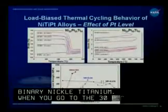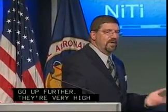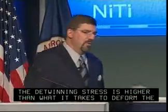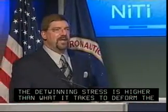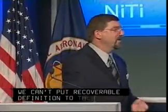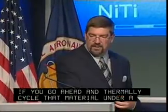In fact, they're very high now. And the detwinning stress is now actually higher than what it takes to deform the austenite. So we're back to that original condition. We can't put any kind of recoverable deformation into the alloy. We can't detwin it, but at the same time, if you would go ahead and thermally cycle that material under load, you're going to deform it plastically because of the austenite deformation.